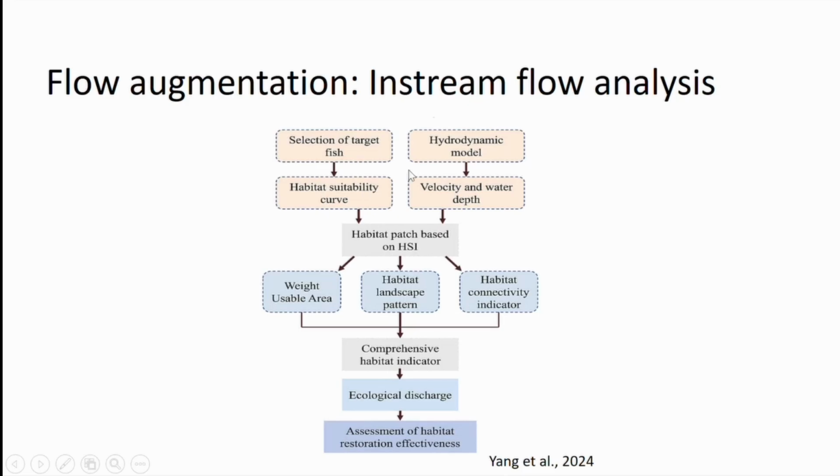And so we combine the two to what we call hydraulic suitability index and create a map to show locations alongside our river body where fishes can survive at a given flow rate.